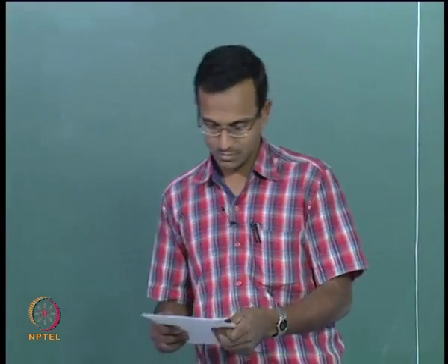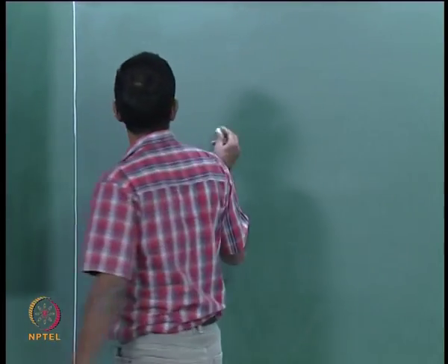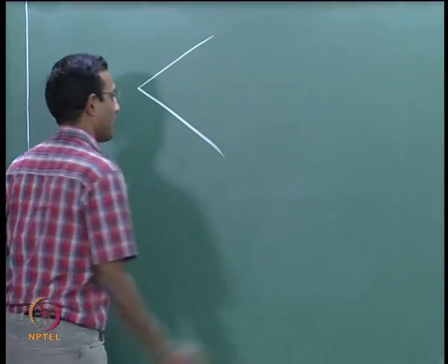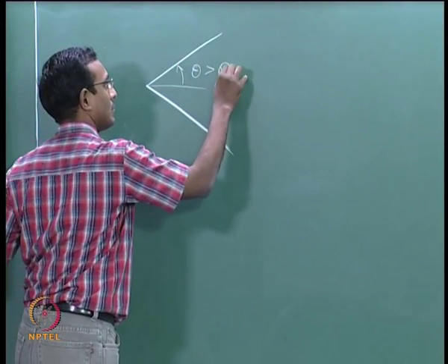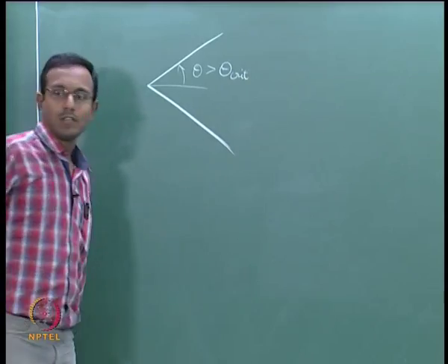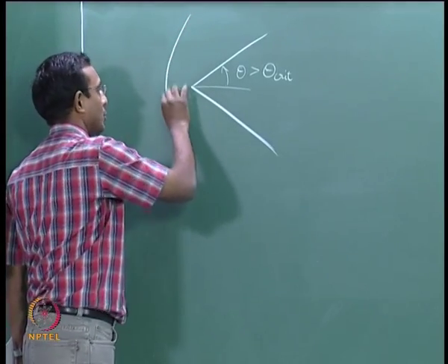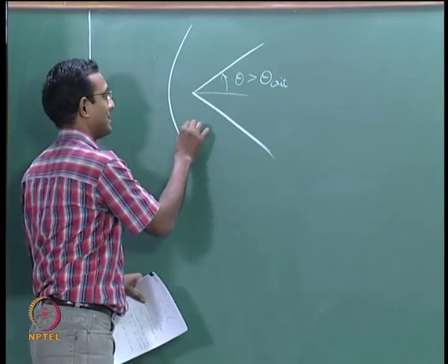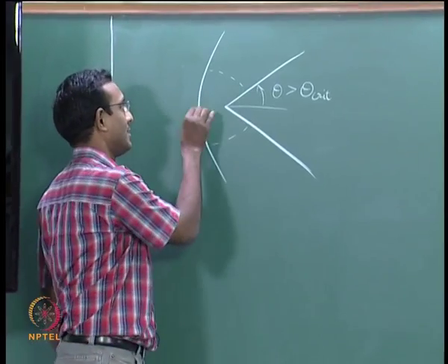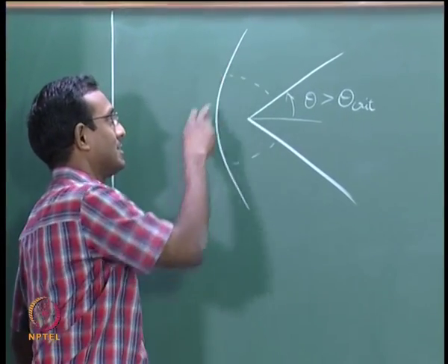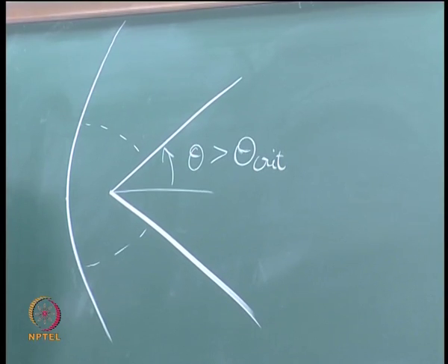Everyone, welcome back. Last class we stopped with the discussion of flow over a wedge with the angle more than critical angle, and we said that the flow will have a bow shock, and this flow is more complex. It is going to have a subsonic pocket, and then the flow accelerates to supersonic across it. And we said that the shock angle, if I go along this line, starts from 90 degrees and decreases all the way up to the Mach angle. All that we did last time.